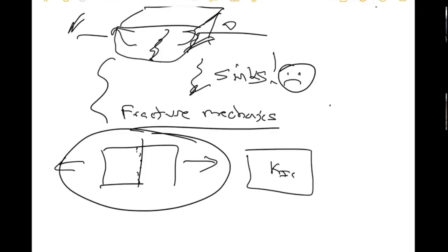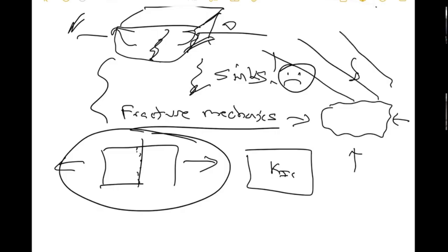It may not be as applicable for an excavation deep underground. But maybe there's a joint set like this, and you could start thinking of those joints as being like those welded joints, and think of this in terms of fracture mechanics and fracture toughness.